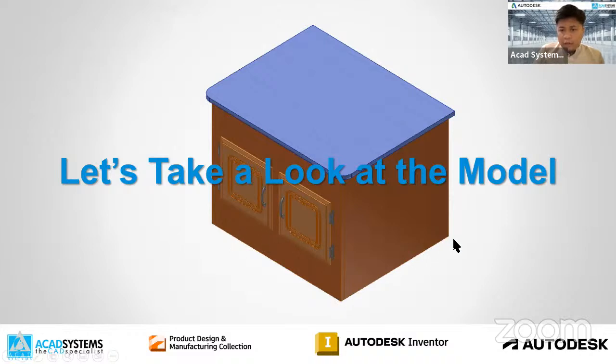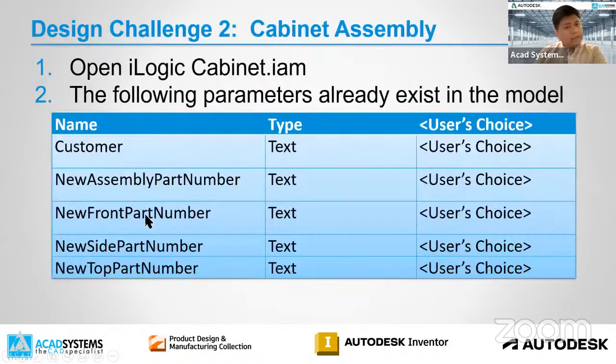Over here, you will see they have length, width, height, also the door size, together with the opening. For this model, the size keeps changing. I don't have a very constant, very simple size. So what I need to do, first step, open the file, the IAM file, and then directly create a user parameter, just like before.